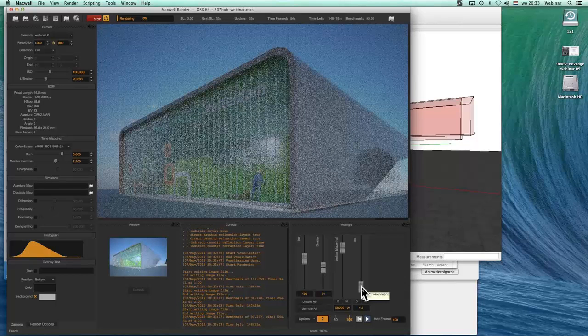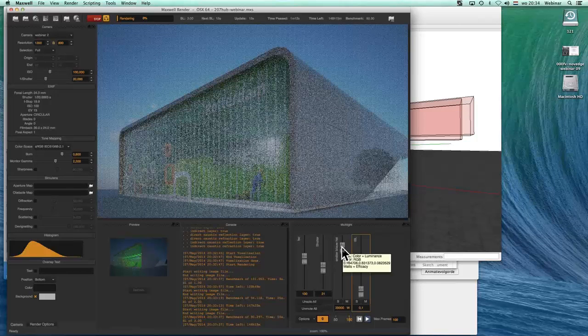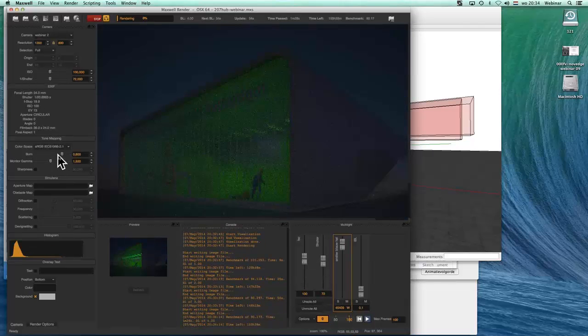But as you can see here, this building is a modern industrial building. The bigger image is what it's actually rendering, and the smaller image is a preview. So if I switch off the illumination from the background or the HDR, I can lower the lights within the building or give it more light. I can adjust shutter speed. I can also change a little bit of the monitor settings, maybe here with the vignetting.